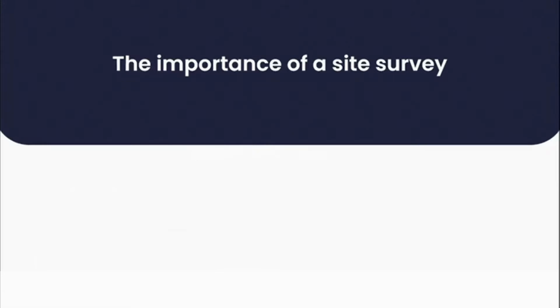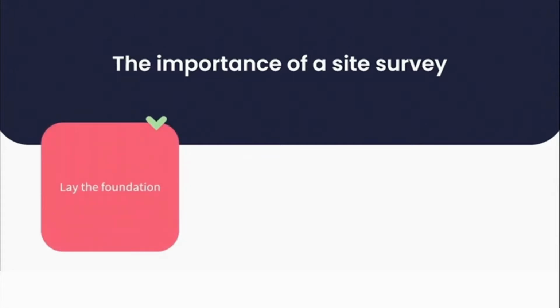Here's why. Firstly, your site survey will lay the foundation. The site survey is the starting point to any project. I cannot stress this enough. Without the site survey, you cannot begin to design anything. When designing without a site survey, this is called designing blind, and I never recommend this as a way to start off any project. The site survey will provide you the starting point of detail, notations, dimensions, and most importantly, a feeling for the space.